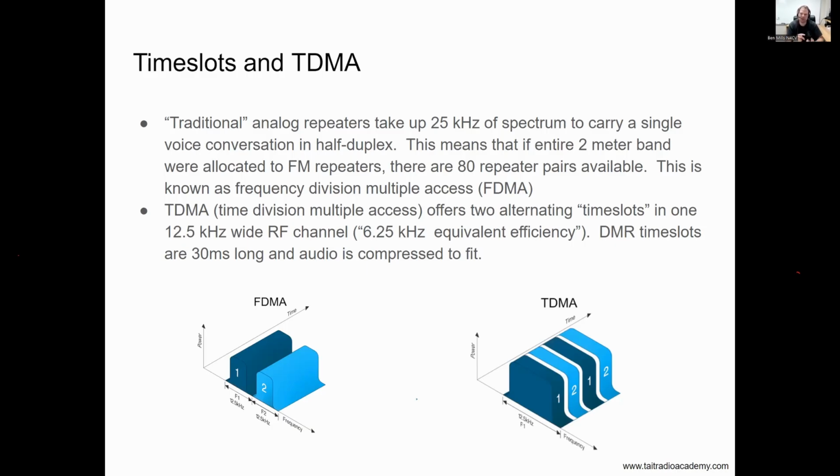There was a Baofeng radio that came out a number of years ago that was DMR capable but non-compliant, in that they used their software-defined magic to create a DMR radio that transmitted every 30 milliseconds, but it keyed up the entire time. It was sold, people used it, and people quickly discovered that their radio PA was 100% duty cycle, thus jamming the other time slot when they weren't talking.